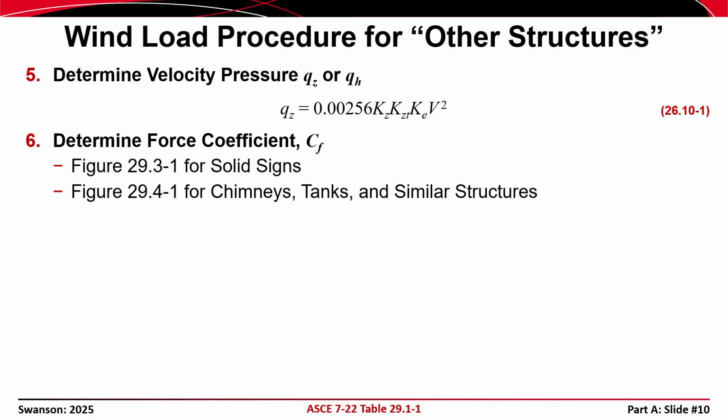These cases refer to different wind loading patterns that are required because the wind doesn't always blow perfectly straight at the face of a sign or a building, and because it rarely exerts a uniform pressure against the sign or the building. Thus, the code often requires us to consider multiple scenarios of wind loading. We'll discuss this in more detail later.